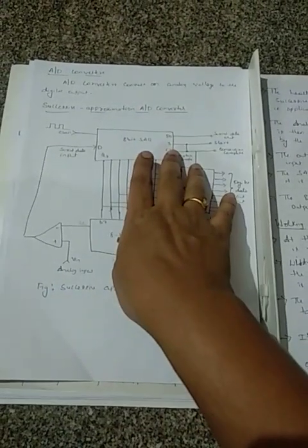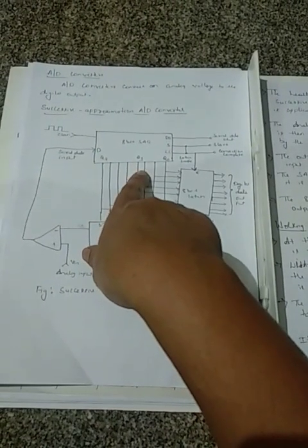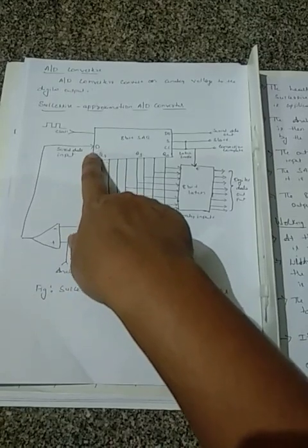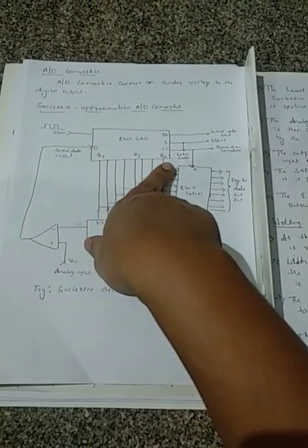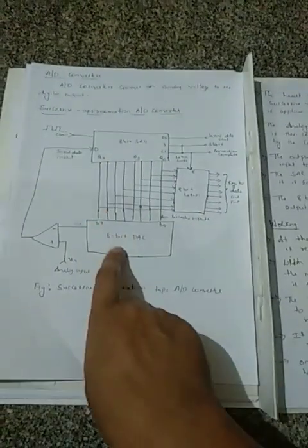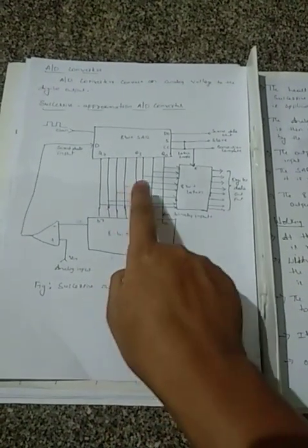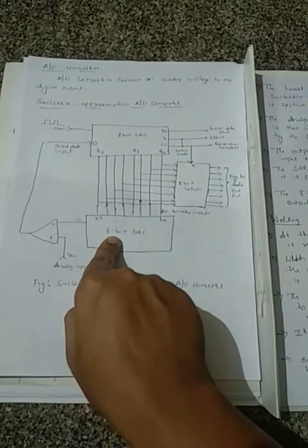Okay, I'll repeat again. Now the 8-bit SAR will be reset. Upon the next clock cycle, Q7 will become high. This is trial and error. This input will be given to the 8-bit DAC, which converts this digital data into an analog output.